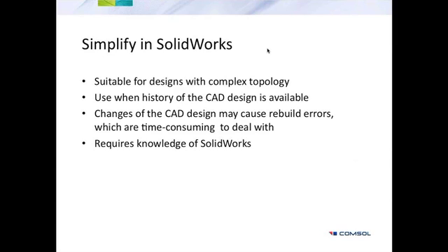If a CAD design has been made in a way not following certain design rules on how to apply the features, then if you make a change, it would cause a lot of errors when you're rebuilding your design. So that is something you have to weigh